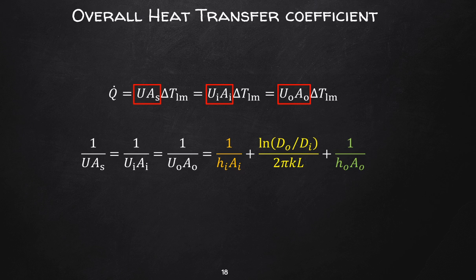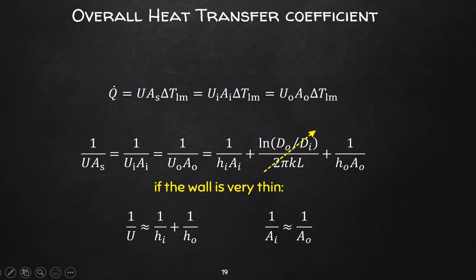Now, every heat transfer equipment has two surface areas that it deals with: A_i and A_o. So A inner and A outer. Even plate and frames, obviously, it's the same surface area. So only for, okay, let's talk shell and tube, only when we have a wall thickness that is small enough and the thermal conductivity of the tube material is high enough, as in the case of using copper or aluminium, we can then equate these two coefficients and adopt a universal overall heat transfer coefficient.